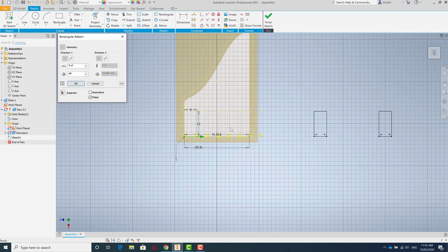Now it looks like that if I'm trying to fit all those parts in, the gaps between them are just going to be a little bit too small. But what we can do here is really test that by saying, okay, we want them fitted edge to edge in 30.8 millimeters, but actually I want them to fit into that distance minus the width of the last key, which is 6 millimeters. Or if I'm being really clever about this, I can actually select that dimension there. And now we've got them fitting right into here. So it's measuring from this edge to that edge, fitting them into a shape that is this dimension minus that dimension, which gives us the exact distance that we want.